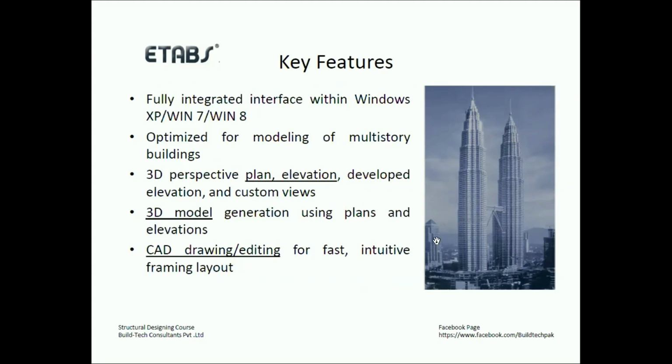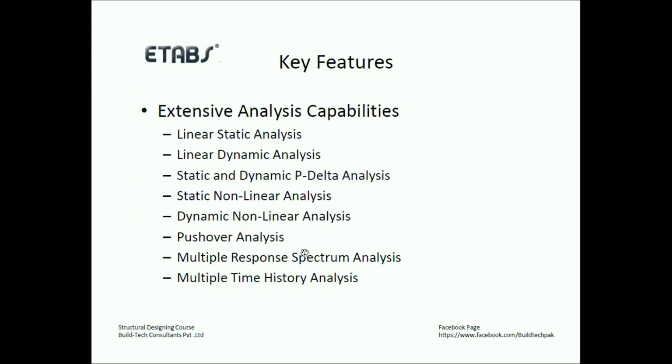It's not like you directly import the CAD file you got from the architect, because that CAD file contains so many objects. It has windows, brick walls are shown, columns, everything. So you just need some grid lines and columns there. So you need to do some adjustment on those CAD drawings, and once it is done and cleared of all irrelevant things, then those CAD drawings can be imported in Etabs as well.